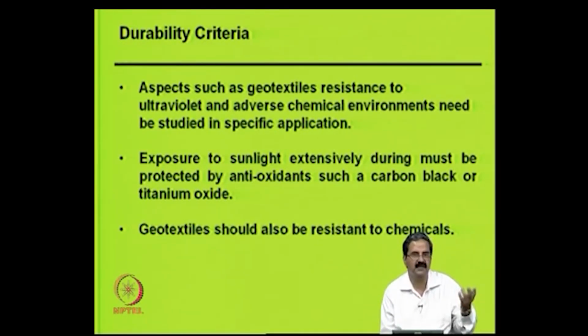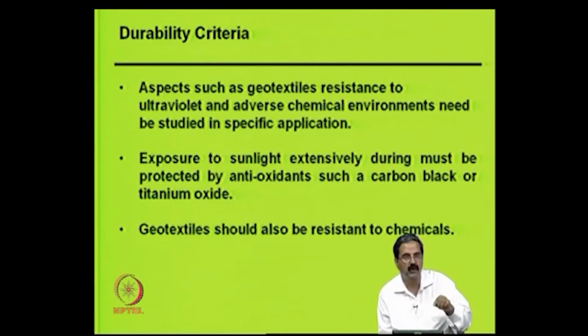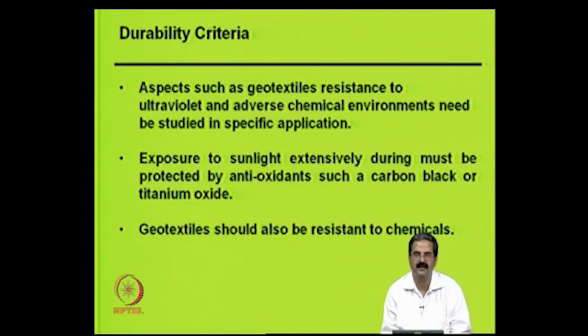In a conventional geotextile design, what are you doing? You have only 2 criteria that we are doing. One is just the soil retention criteria, the other one is the permeability criteria, using those D60, D10 sizes, that is all. There is no other design method, but Giroud has looked into it in more detail and looked at all these factors and come out with a design method which is quite reasonably well established.